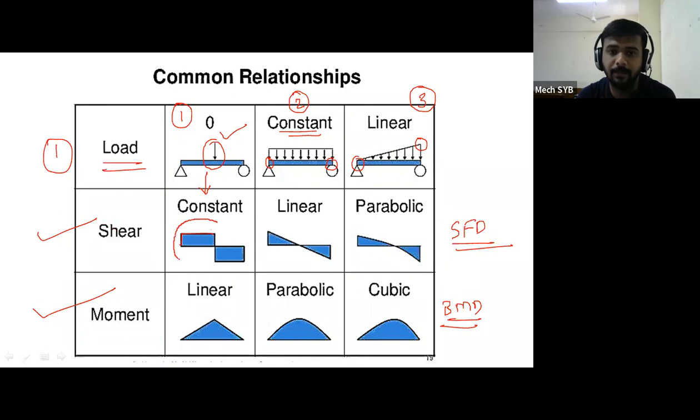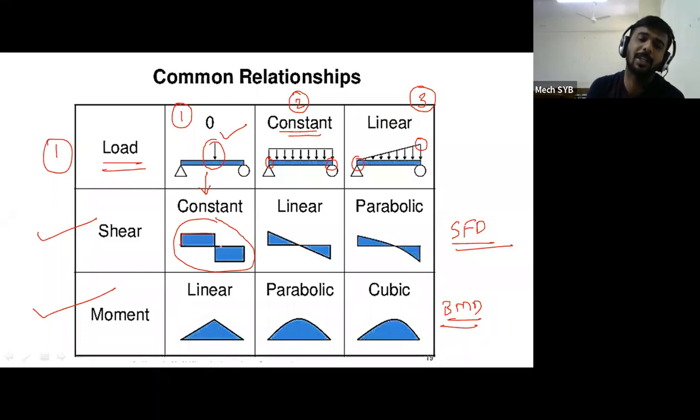If you see this particular figure, there are only vertical lines and horizontal lines. In this second row, if a point load is applied on a beam and you look at its shear force diagram, you only see horizontal and vertical lines. What is the meaning of that? If your beam is subjected to a point load, then that point load's SF calculation will be represented in the form of vertical lines and horizontal lines.